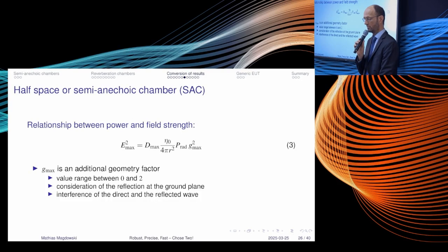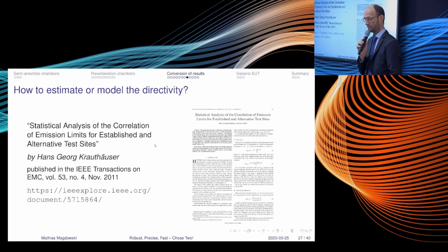And we can more or less apply the very same formula also in a semi-anechoic environment. But here we need to include an additional geometry factor that takes into account the reflection at the ground plane and the superposition of the direct and indirect path. So this is all known. Still, we need to have this directivity there.